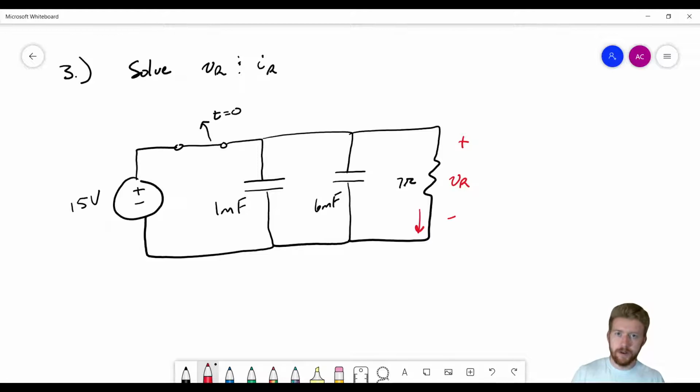So this one, we've kind of seen something that looks like this before, right? Because we looked at what happens when capacitors discharge in the capacitors video, but we haven't looked at one like this where we have 2 different capacitors. So how are we going to handle this? Okay, well, hopefully you watched my last video, which talked about how we can combine capacitors and inductors. So what we can do here is identify that we have these 2 capacitors in parallel. There should be a way to combine them into an equivalent capacitance.